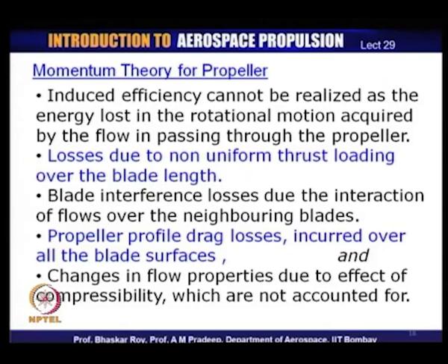The next point is the propeller profile drag losses incurred over all the blade surfaces. Now, we do not have blades over here, there are no blade surfaces. So, the aerofoil is absent and hence there is no surface whatsoever, and the drag that aerofoils encounter in the process of creating lift is completely absent. So, the propeller does not experience any such loss as it is modeled in actuator disc theory.